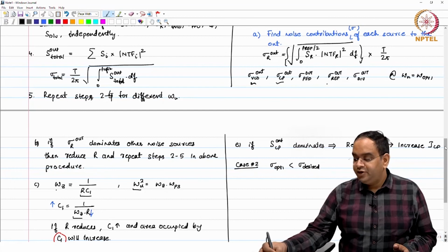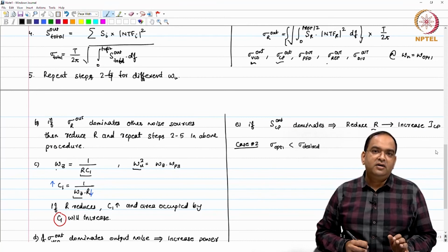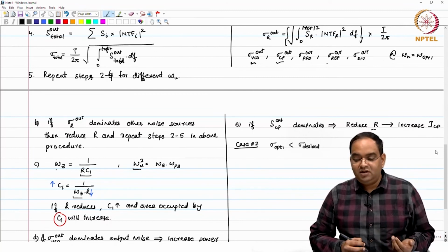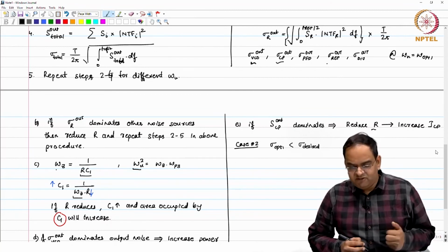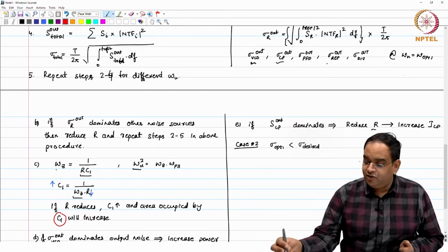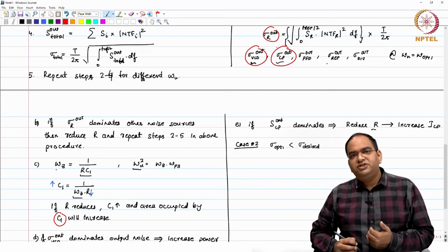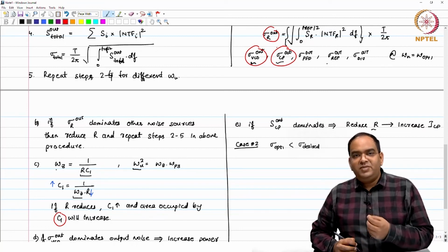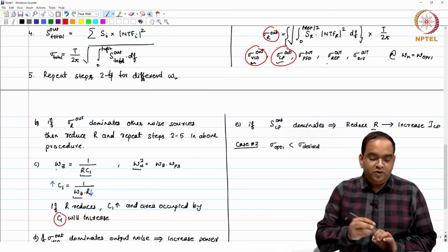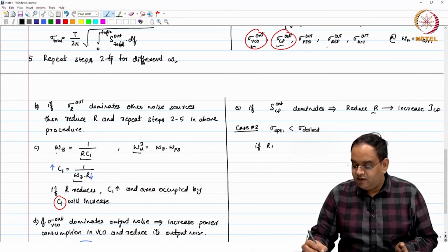Okay. So, in that way you can go ahead and find out, sigma, VCO and all those things, you find here that which of these noise sources is least dominant. Okay. So, reference is coming from outside, you have divider, you have your PFD, charge pump and so on. So, once you find which is least dominant, mostly it will be either your R or VCO or charge pump plus PFD. So, you find which one is least dominant, and based on that you reduce the power consumption in the design.